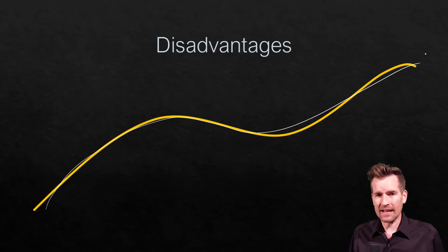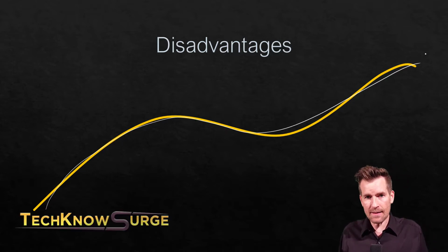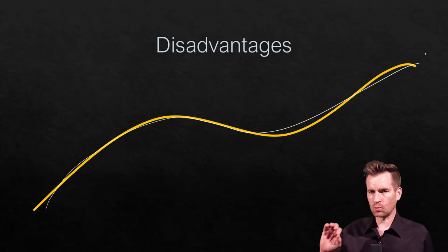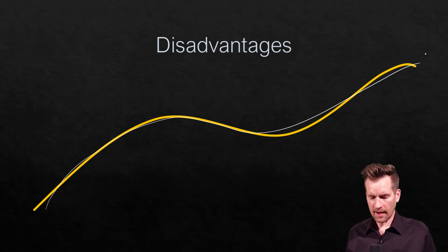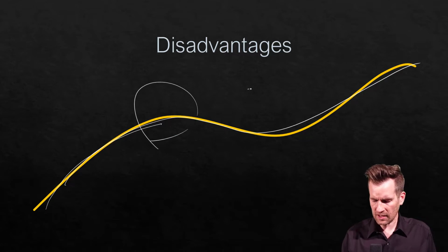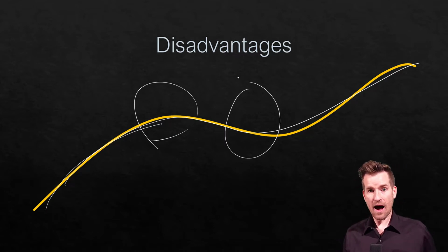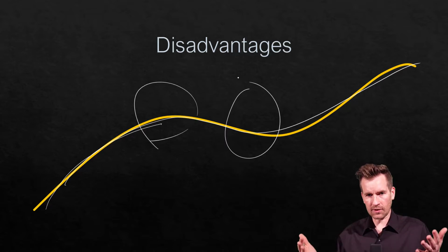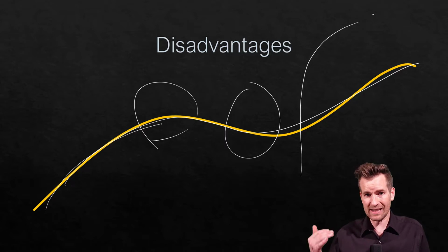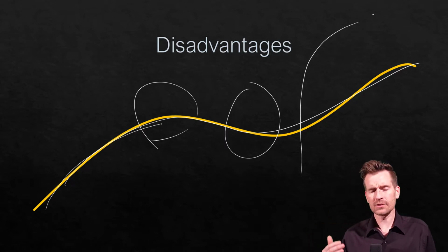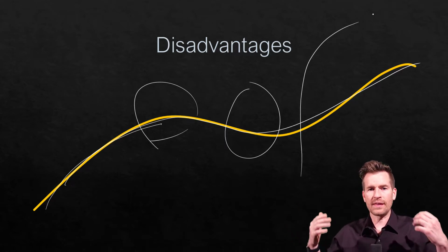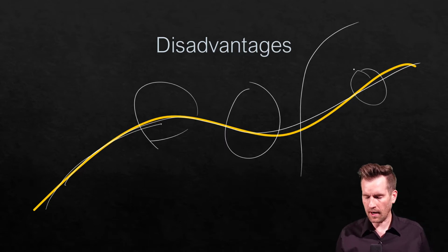Another thing is that these lines are susceptible to EMI, or electromagnetic interference. When electrons run through a cable, it lets off these fields. Different cables can interfere with other cables. So for instance, let's say a power line runs across this, or even worse, next to it. The electrons running through that power cable can create these fields that will then interrupt the electrons within our data communication.